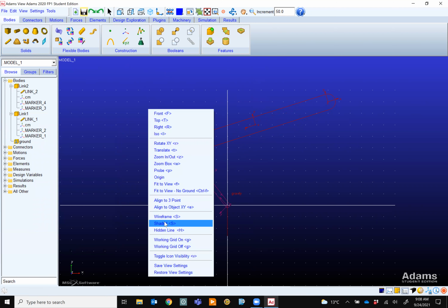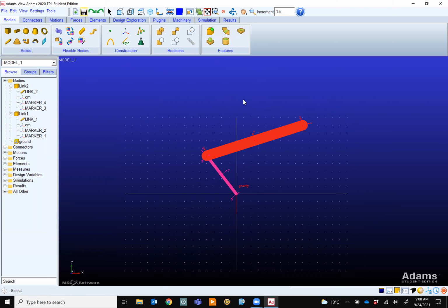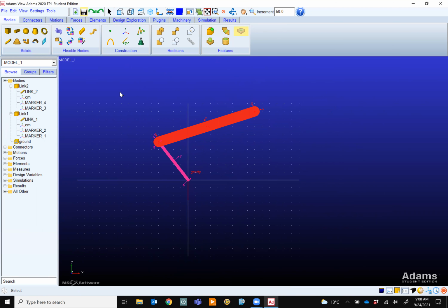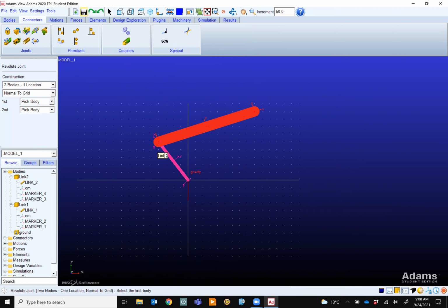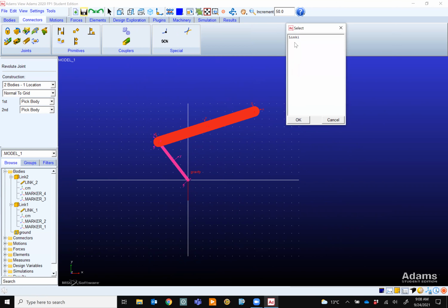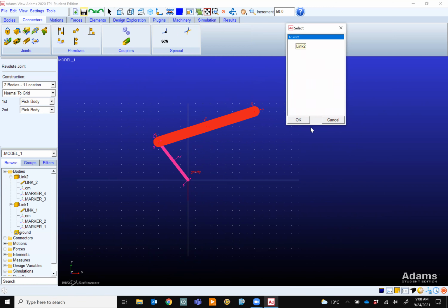Let's shade these things so you can see what is there. So now, if I run it, you know what will happen, everything falls off. Let's connect them together. So I connect, this is the connection with this joint. I connect link 1. Let's right click to make sure we are selecting link 1 to link 2.